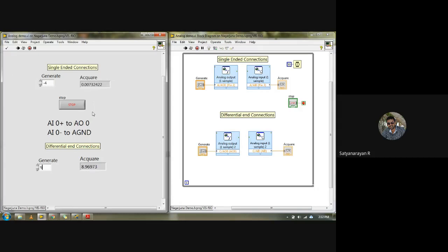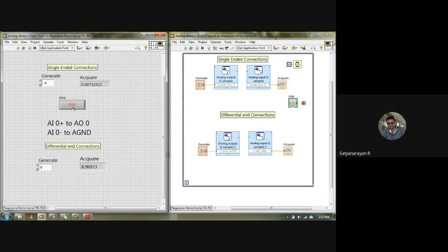That's what I'm telling you. Before selecting the hardware or the sensors, make sure you are selecting the right hardware or right sensor, so that the voltage range does not fall outside what is required, either more than the given voltage or very much less. Maximum, what we have seen is that we can go with nominal sensors like 5 volt, 10 volt or 12 volt. If you want to go beyond 12 volt, maybe I have to go with some industrial sensors.